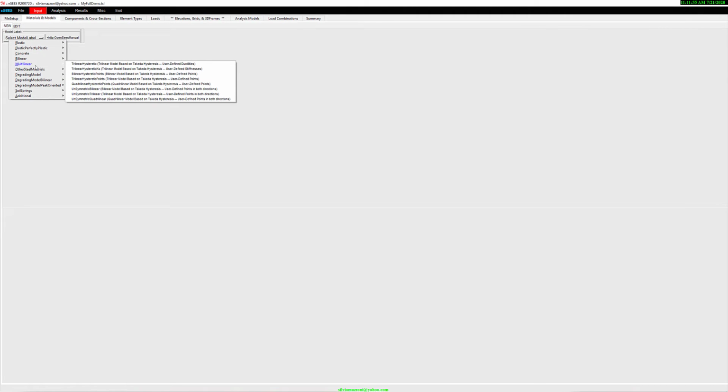There are so many different options that you can do for steel. And this gives us an opportunity to look at these different material types and how I've grouped them. So we've got the bilinear model. The bilinear model has 3 different options. One is looking at Steel02 and Steel01, which are purely bilinear, or using the hysteretic material in OpenSees, but where I've given you just the option for 2 values. And so the second stiffness actually goes on to infinity. So you can pick one of these 3 if you want a bilinear model.